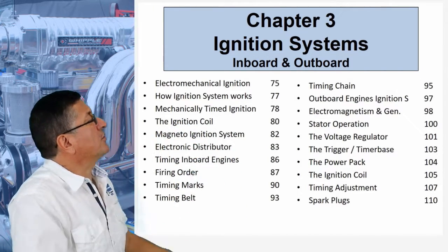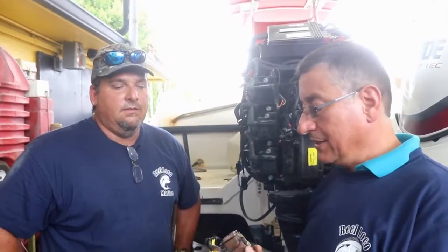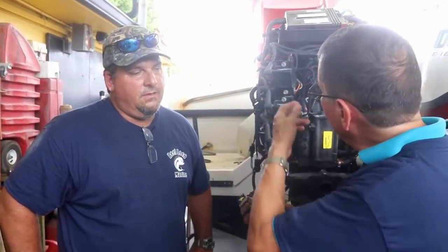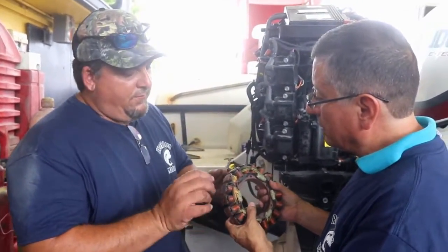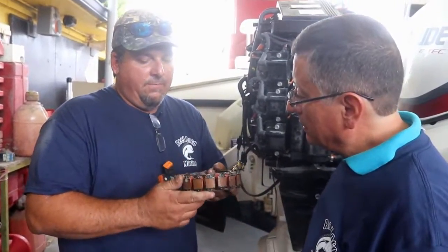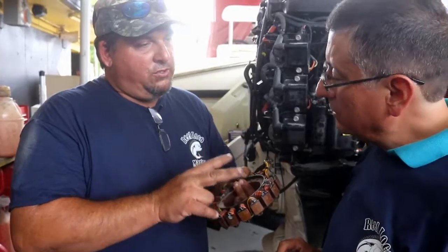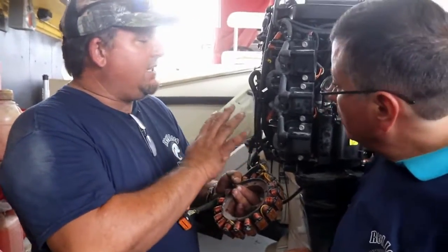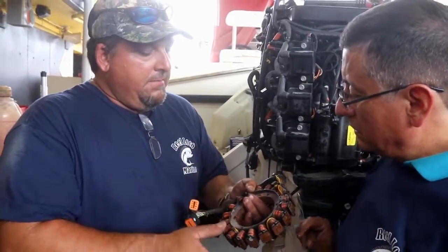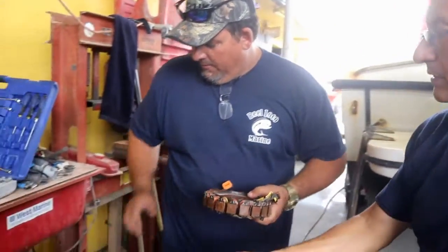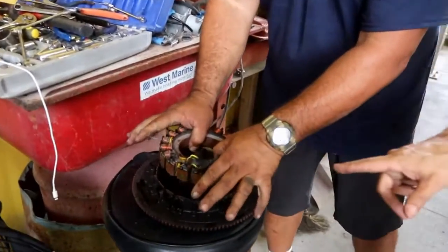How is that conversion, Mr. Rodriguez? Danny, how can you get 55 volts on the injector? Alright, so the 55 volts comes from the stator. There are two parts to the stator, so basically it's like having two stators in one. And what happens is the engine actually has a capacitor, which I'll show you. But how this works is if you come here, that's the flywheel.